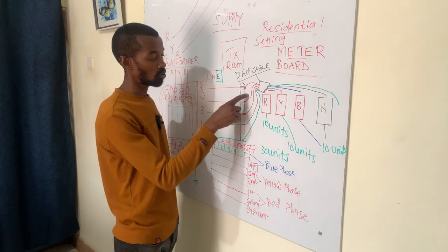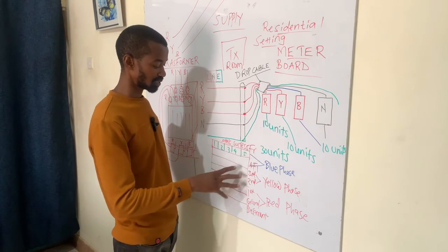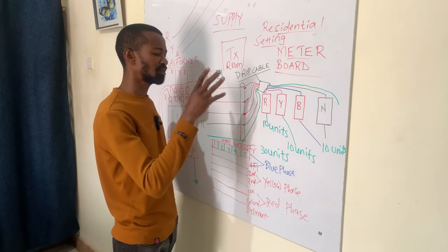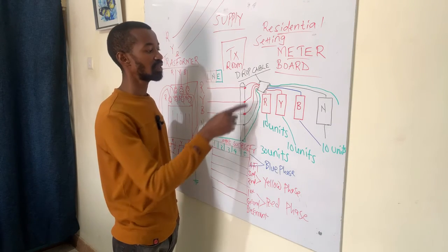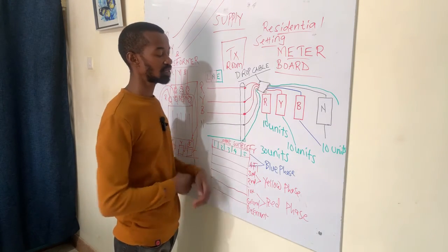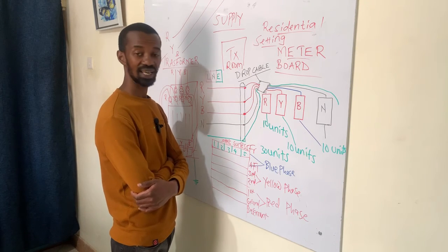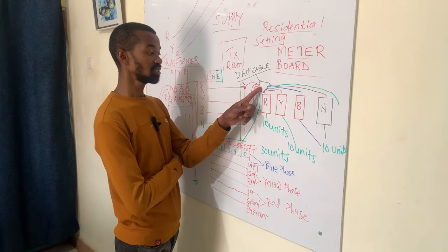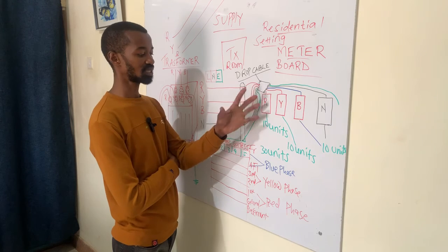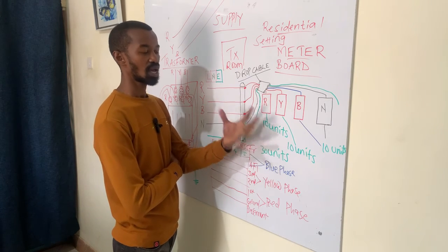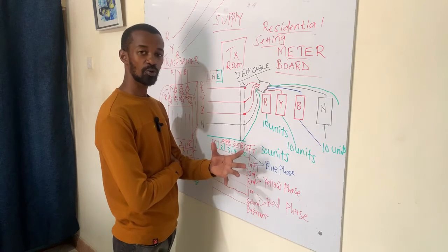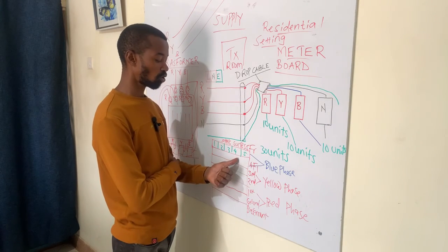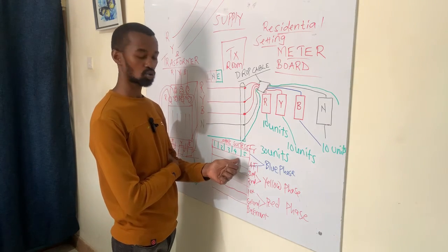The type of load that you expect there, you must be able to fill in that form, the load, so that the cable that is distributed to your client's apartment is the correct size, so that it can be able to handle the load. Again, you must be able to assume the scenario whereby all of these customers are at home.